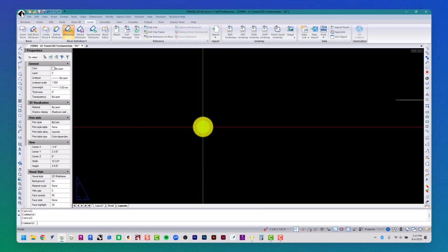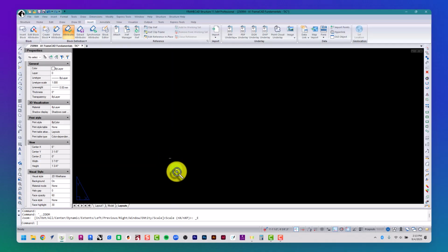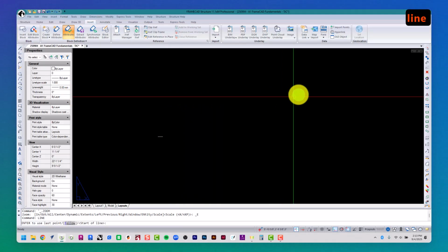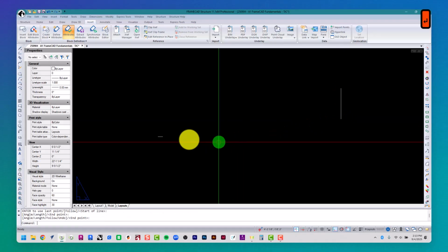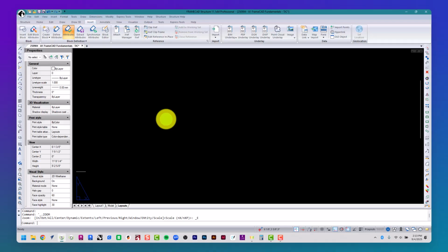So if I were to zoom way out into the universe, type in line, space bar, put it over there, zoom into this one here, and then double click on my middle wheel button, it'll bring all the geometry right here in the forefront in my modeling environment on my display. So I'm going to go ahead and delete all this and make a nice large selection window. I can select both of those items and I'm going to hit delete.